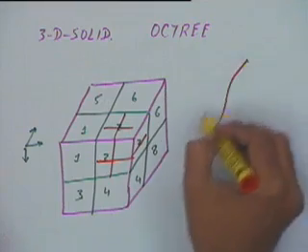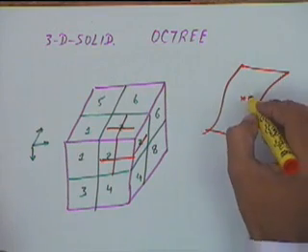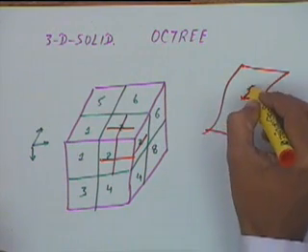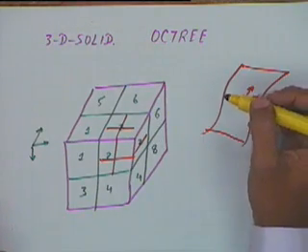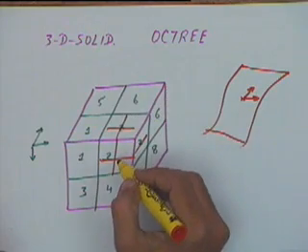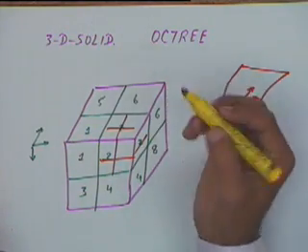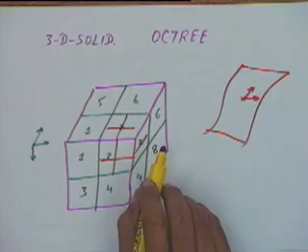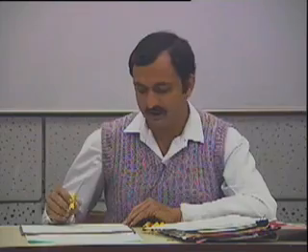Normally, if you have a 3-dimensional surface and you want the surface normal at any point, you can compute the derivative in one direction, the derivative in a second direction, and take the cross product. You will get a surface normal. But if you have a model represented in octree representation, getting a surface normal is not very easy. The best that can be done is you draw each of the cubes independently. The surfaces of the cube which are visible, you keep drawing one after another. Once you have a good enough representation, you stop. That is the way display is normally generated.